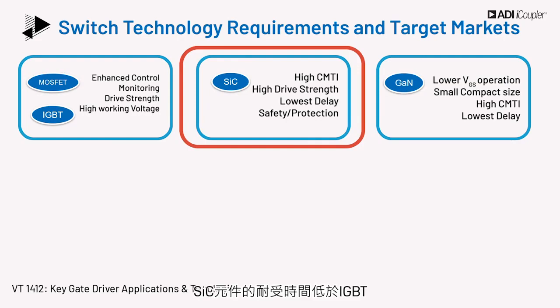The withstand time of SiC devices is lower than IGBTs, and hence for safe device operation, faster response and lower delay is necessary, which is also supported by ADI drivers.